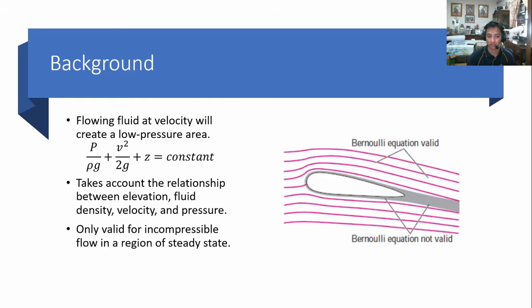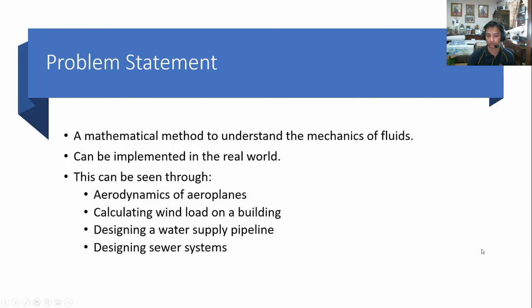The static head does not incorporate any dynamic effect. It represents the actual thermodynamic pressure of the fluid. Next, the dynamic head represents the pressure rise when the fluid in motion is brought to a stop isentropically. The elevation takes into account the reference level selected, which includes the effect of fluid weight on pressure.